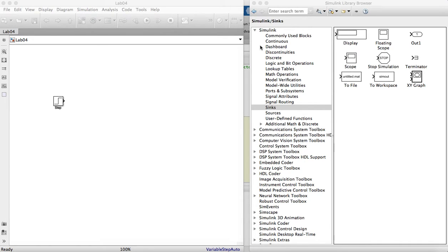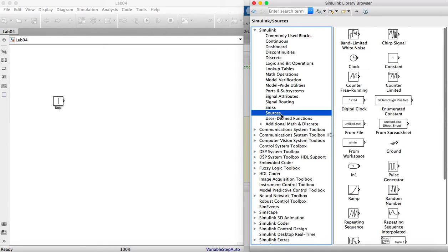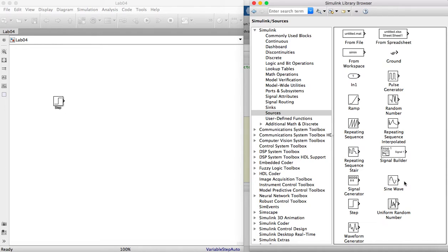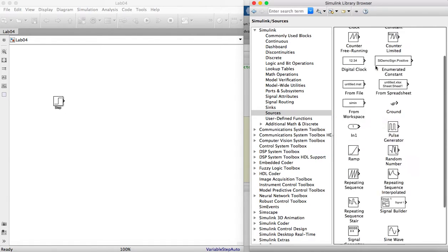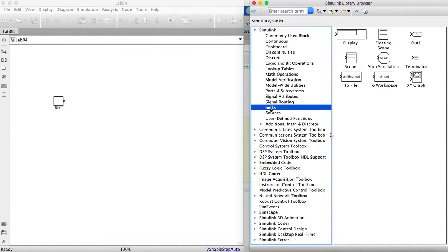Hello everyone, welcome to the second part of the introduction to Simulink and modeling of the feedback controller. In the previous lecture we talked about sources and sinks as the two most important blocks in the Simulink library. We talked about different signals such as sine wave, step function, and also random signals. We also talked about the sink blocks, the scope and workspace, and how we can apply them. In this video, we will talk about other blocks while we are making our simple simulation model.